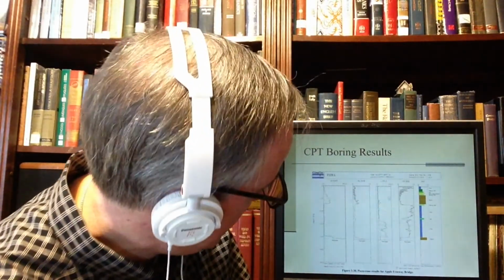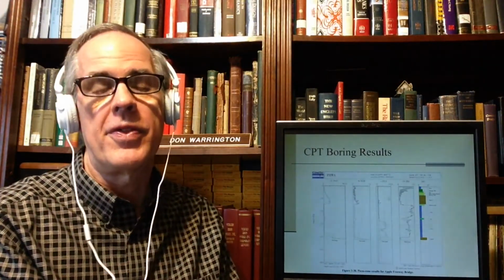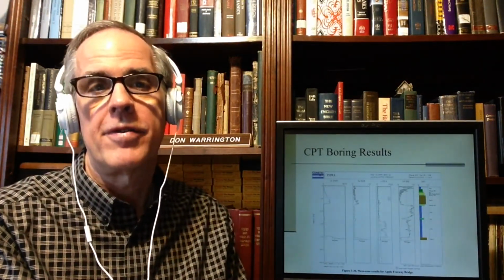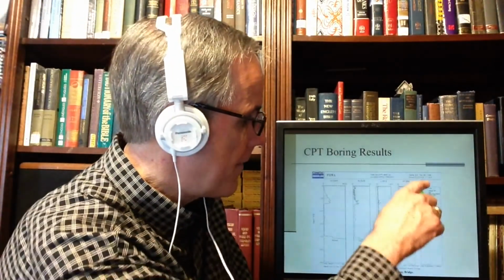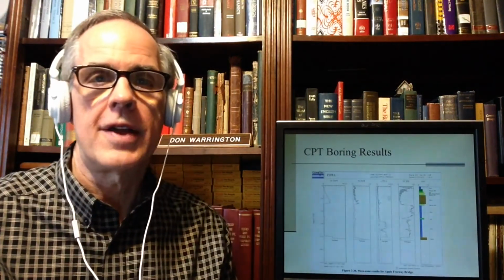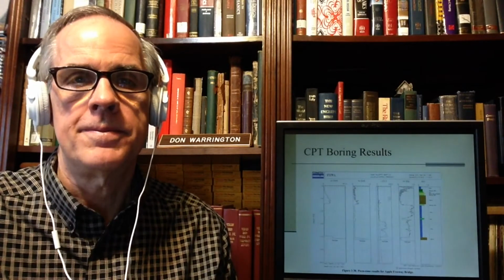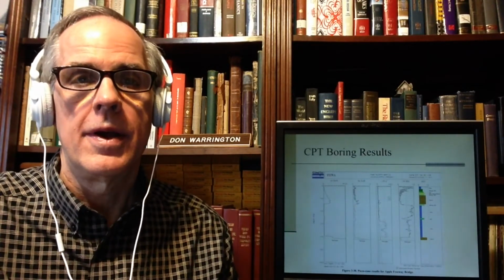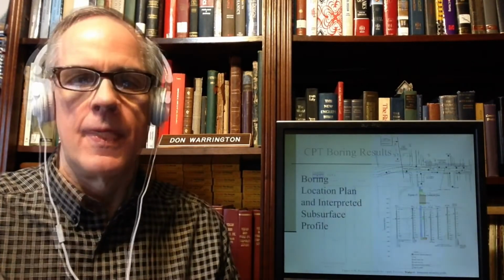You'll see they also have the baseline pore water pressure. I'll talk about what that's all about when we get to effective stresses. But last but not least, putting this data together, you get a continuous soil classification for your site. And that's very important. It's a good, quick way of getting an idea of what's down there.